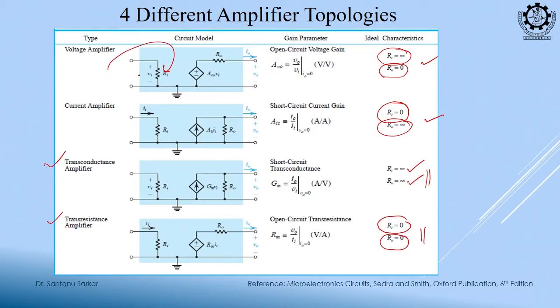If it is a voltage source, the source resistance is in series; if it is a current source, it is in parallel. If you remember these two things, the rest you can automatically calculate. So, you do not need to memorize this, you analyze it. I will not tell you to just remember these configurations; I request you to remember how to analyze, then you can readily recall this.